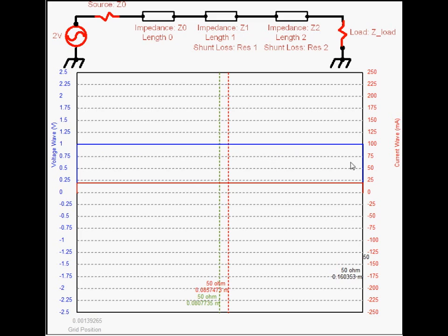So here we have the natural voltage division in the steady state case, not the AC, the wave is traveling down, the wave is settled down. We have a voltage divider relationship where you have this 50 ohms for the source impedance and the 50 ohms for the resistor at the load. So you have the 2 volts across those, that's 1 volt at the terminus, and then 20 milliamps going through, because you have 2 volts divided by the 50 ohm plus 50 ohm, the 100 ohms. That gives you the 20 milliamps.